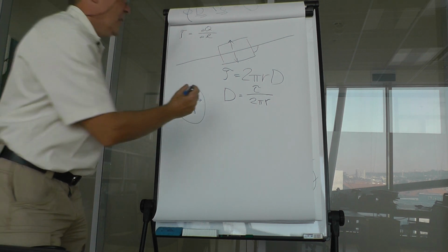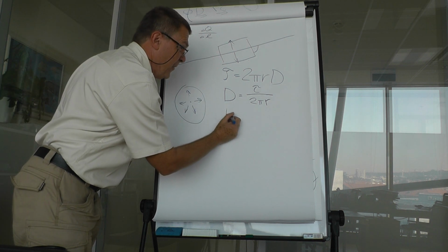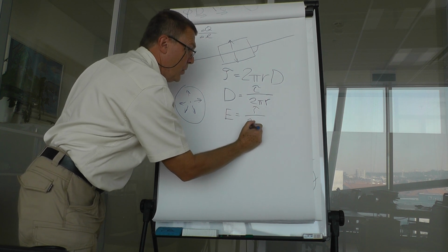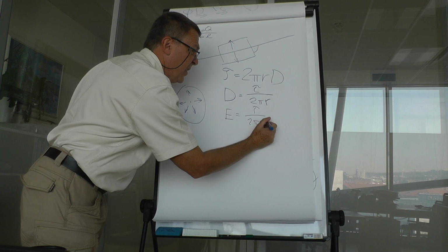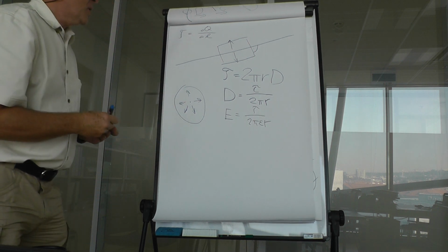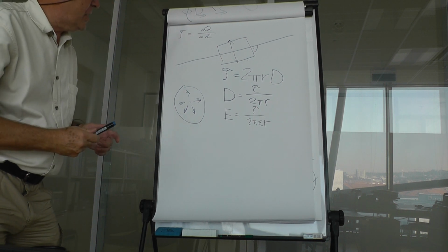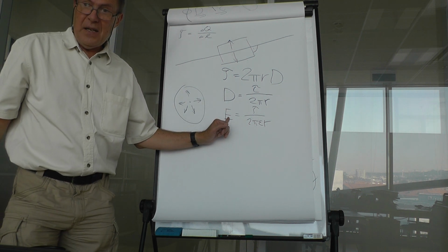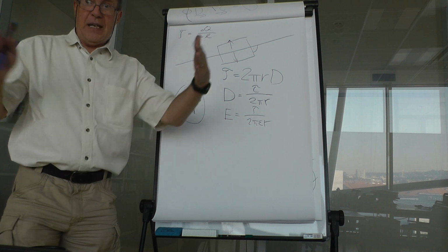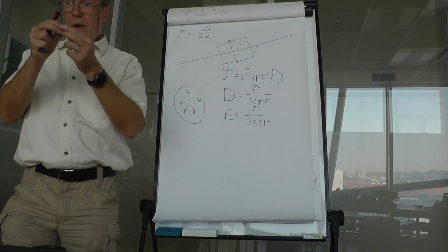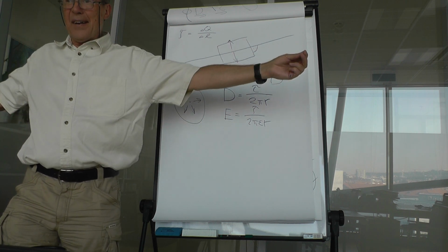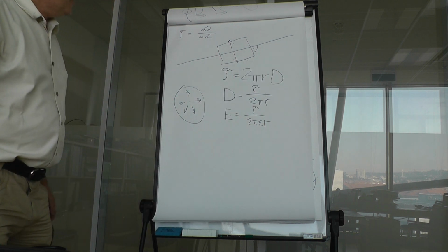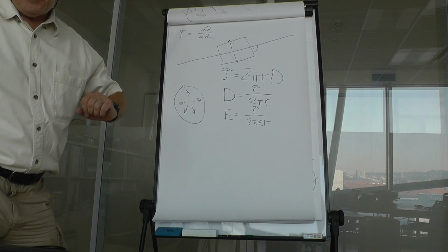And the field strength is tau over 2 pi epsilon r. So now we have established flux density and electric field strength for the second case, which is a universe where only a long wire, which is charged, exists. So this is the second case.